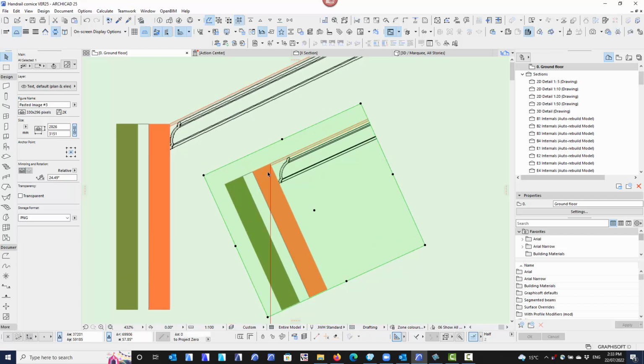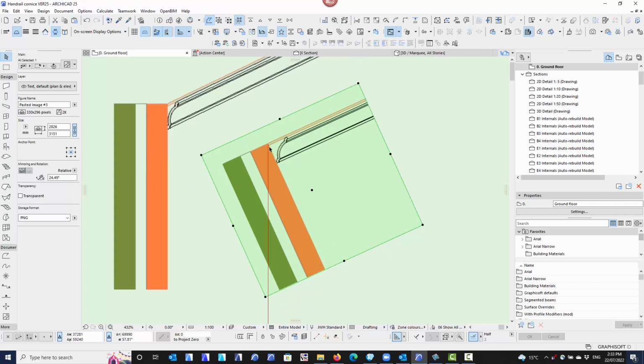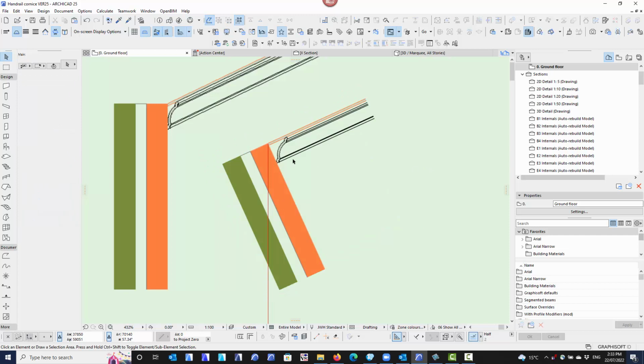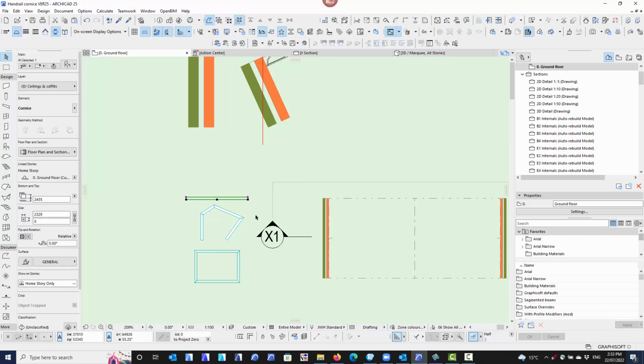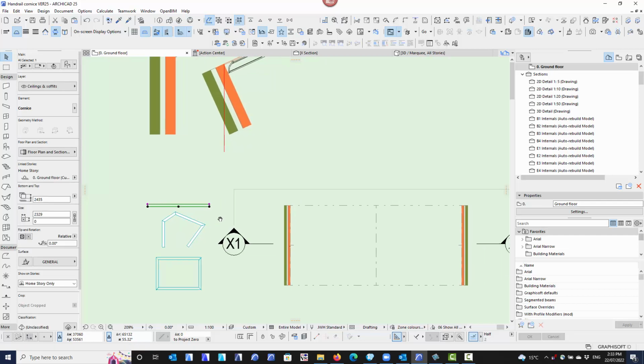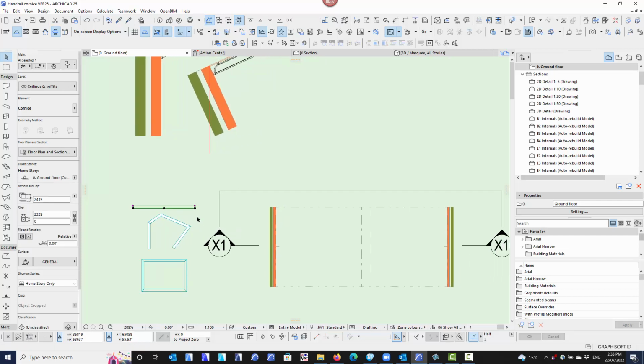Now you can see what happens is obviously the wall doesn't rotate, the wall would stay exactly where it is, and if the wall stayed where it was, there's now a gap. If we take a standard cornice and rotate it, we'll have a bit of a problem here with the gap. Now fortunately our standard cornice takes all that into consideration. We've got some options to rake and roll this cornice.